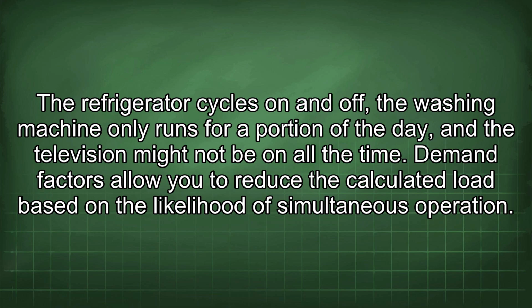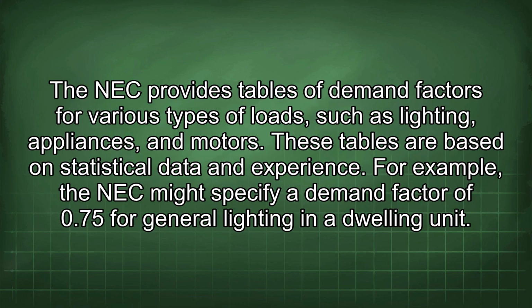Demand factors allow you to reduce the calculated load based on the likelihood of simultaneous operation. The NEC provides tables of demand factors for various types of loads such as lighting, appliances, and motors. These tables are based on statistical data and experience.